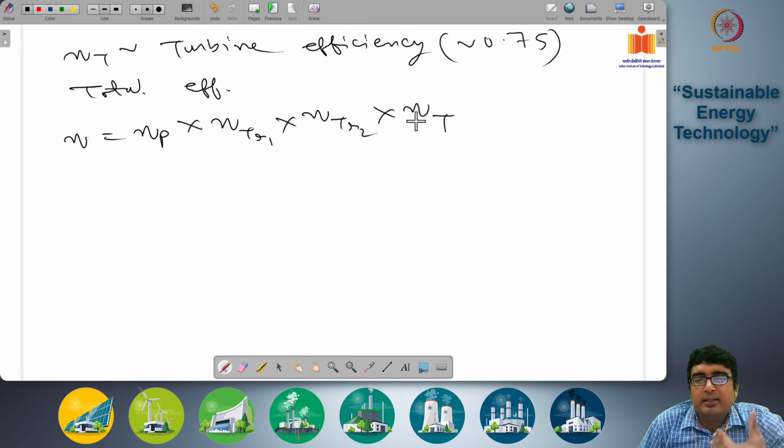Turbine efficiency, the efficiency of the energy from the kinetic energy of water being transmitted into electricity. Okay, so the generator and the motor efficiency are also included in the pump and the turbine efficiency. It's not just the efficiency of the pump blades or the turbine blades. The motor efficiency, converting the electrical to mechanical work, and the turbine generator efficiency, converting the rotation of the shaft to electrical work, are also being considered.